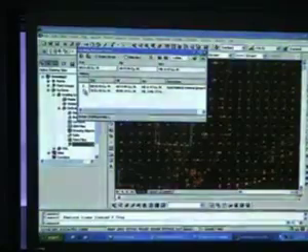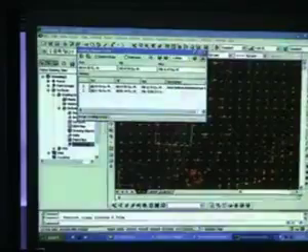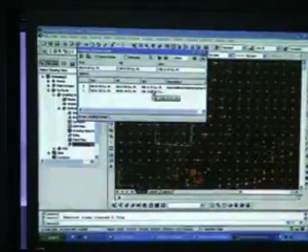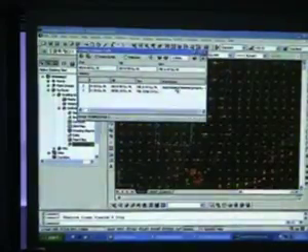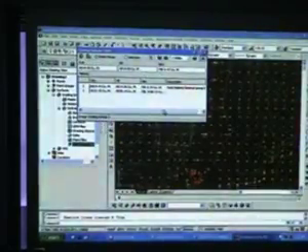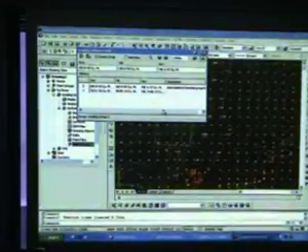So you can see this is the history. That means initially, the first time it was this much. After that, they balanced it. We got this much of cut, this much of fill. Our net volume is maybe 1.47 cubic meters. And it even explains to you what happened. See description: auto balance lowered group. So this is where you can balance the volume, raise or lower the platform.